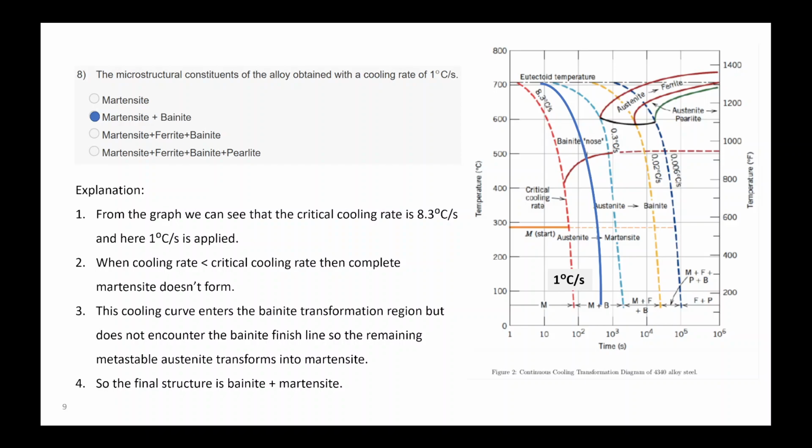Yeah, so the answer will be barrier to dislocation, because dislocation motion is what leads to plasticity in metal. Grain boundaries restrict the motion of dislocations from one part of the grain to the other part, so a dislocation can't move from one grain to another easily. If this is restricted, there will be a pile up of dislocations. This pile up will lead to an increase in strength of the material. That's why the Hall-Petch relation comes into the picture.